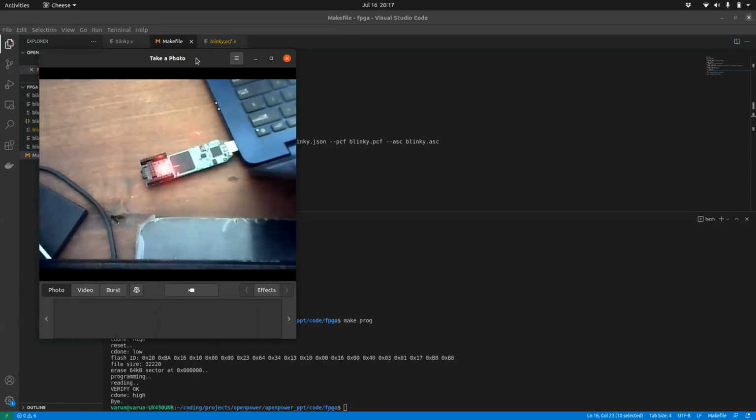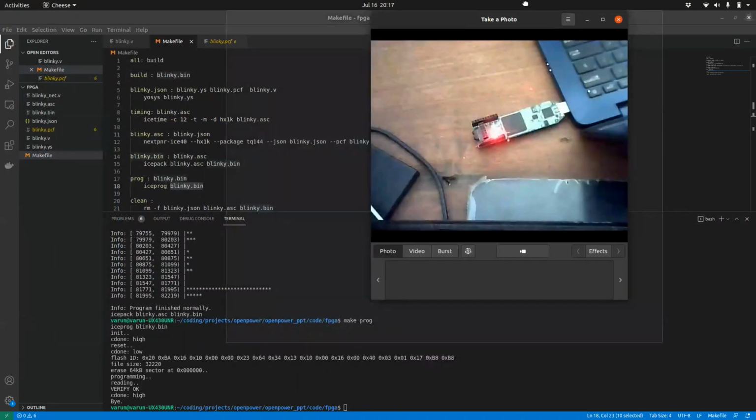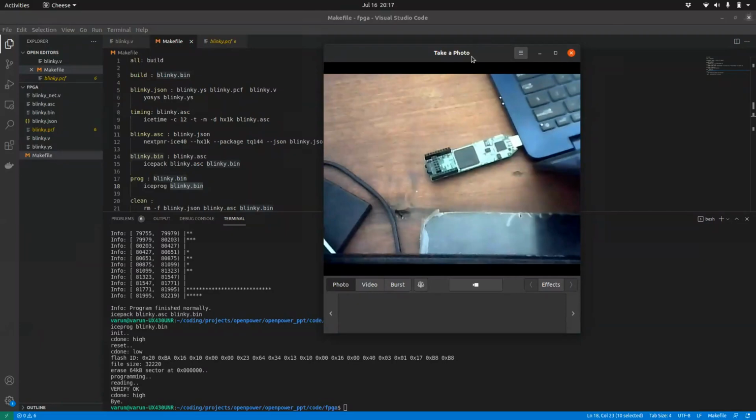The more advanced version with the 85K lookup tables is $130, and you can also get the Digilent Artix A7-100 for about $200 US, which is perfectly capable of running Microwatt and LibreSoc. You're looking at about 20,000 LUT4s for both Microwatt and LibreSoc in the integer configuration. So you don't need several $1,000 Zynq boards, for example, for this. You don't need 300K.